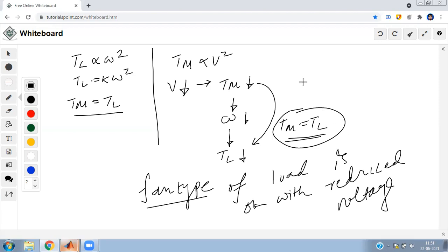Right? Now, what else we need to calculate first is that the motor I have selected is 5 HP, and it is 1750 RPM, and radians per second is 183.16 radians per second. Right?